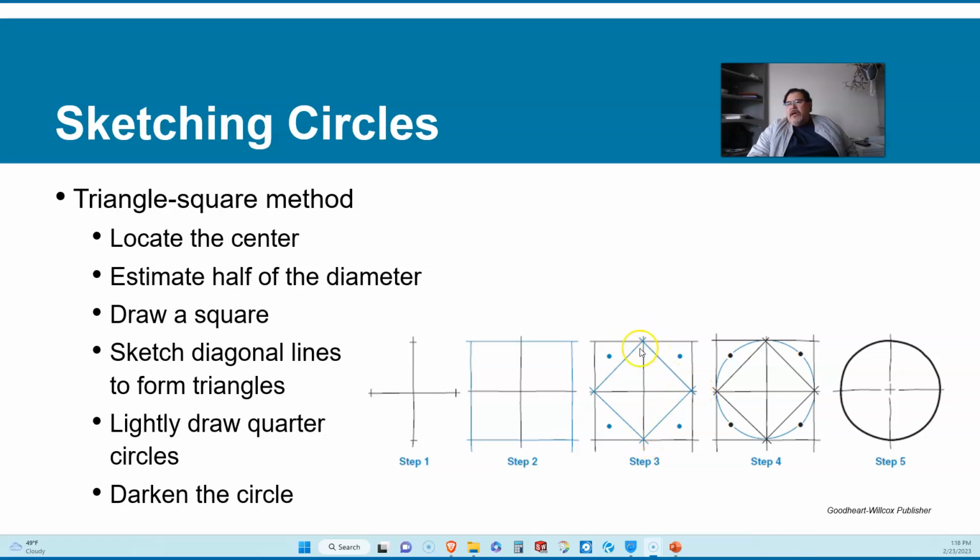You see how the lines kind of go long? Because they extend beyond the point. Because we're just sketching. So you're drawing those with light drawings. Then notice this little center point, which is going to be part of the circle of the arch. It's halfway between the line here and the point of that triangle. It's the middle. And then if I was swinging an arch here, I'd swing it from there to there, this being the center radius. And then you can trace out that line, and you can see its path is going to go through those 4 dots.